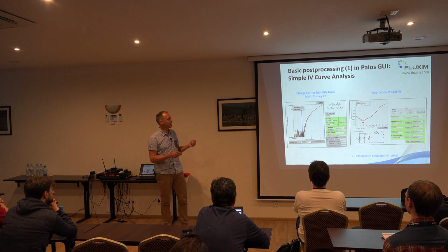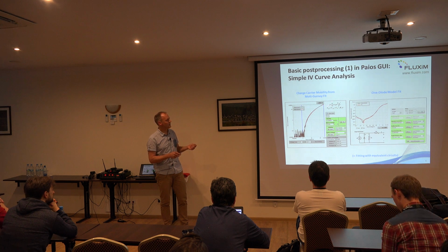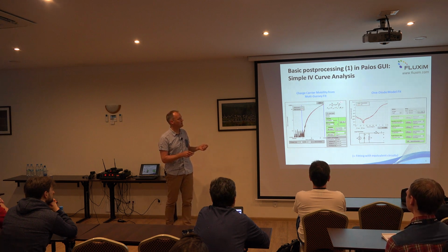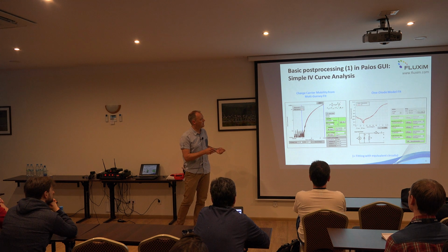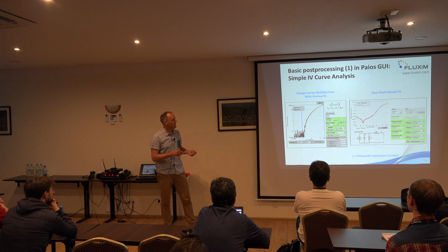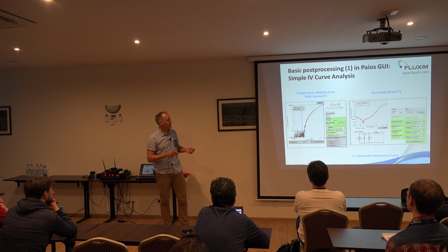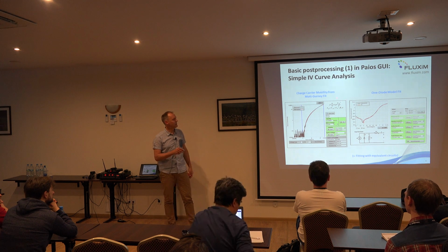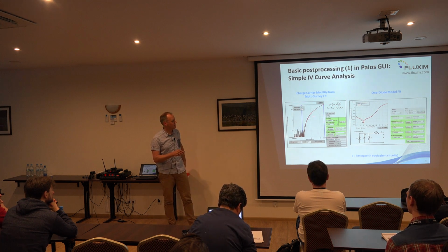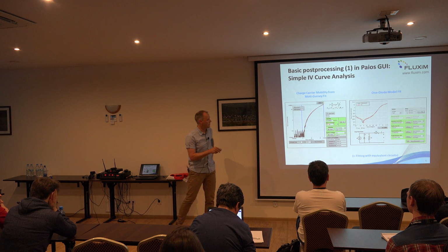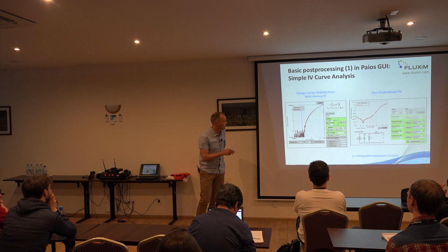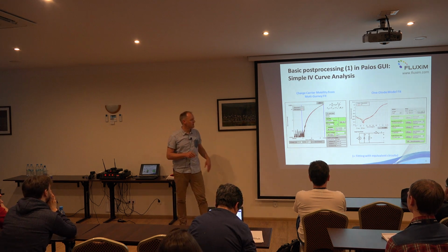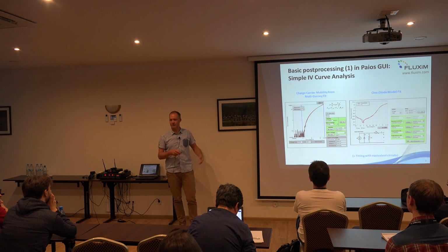If you have space charge limited current, then the current should scale with the square of the voltage and the inverse cube of the thickness of the device. Here you see an example where the black line is the measured data, and in the blue range of voltages you can carry out the fit automatically with this interface, and then you can store the extracted mobility parameter in a database and go on with analysis.